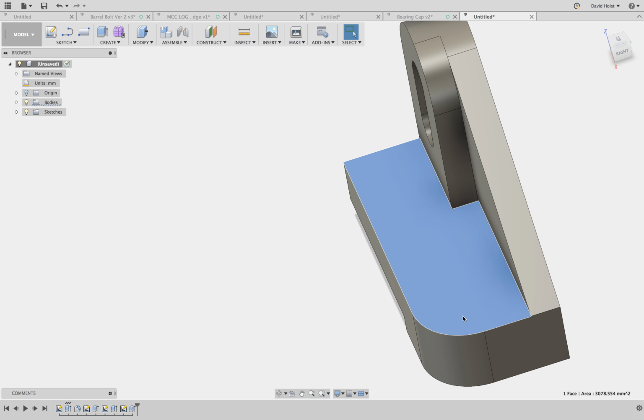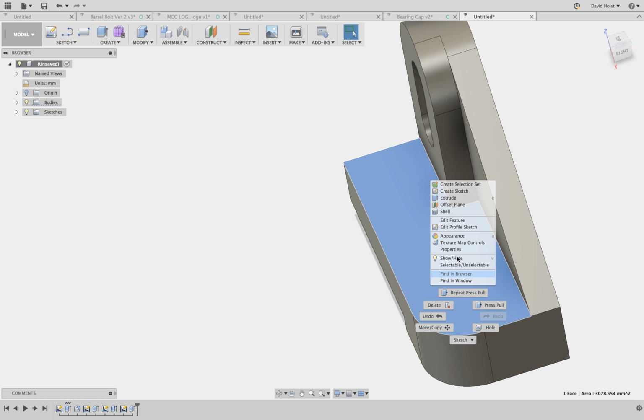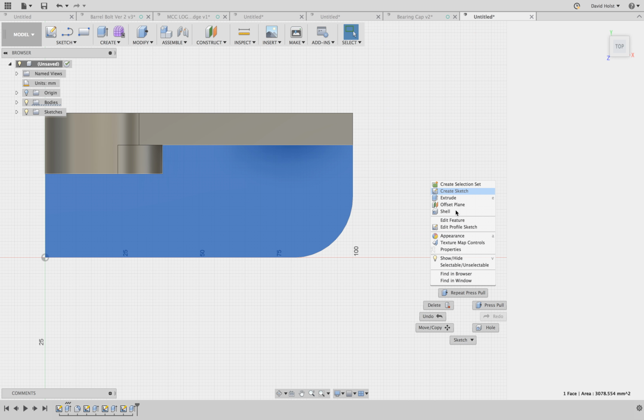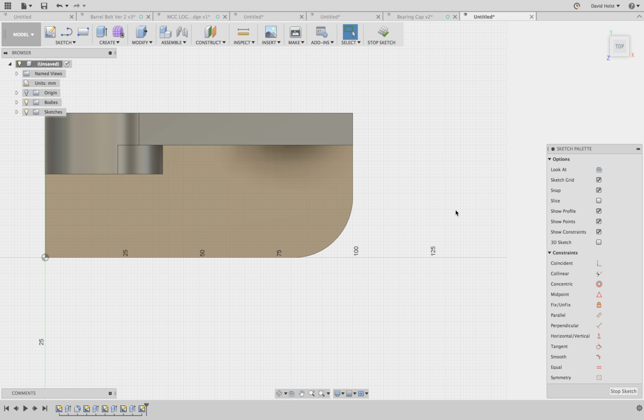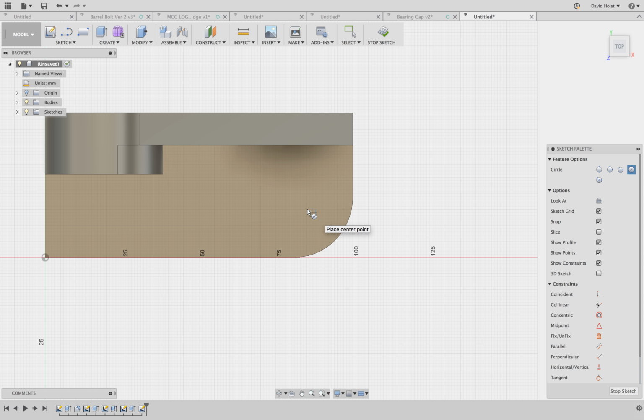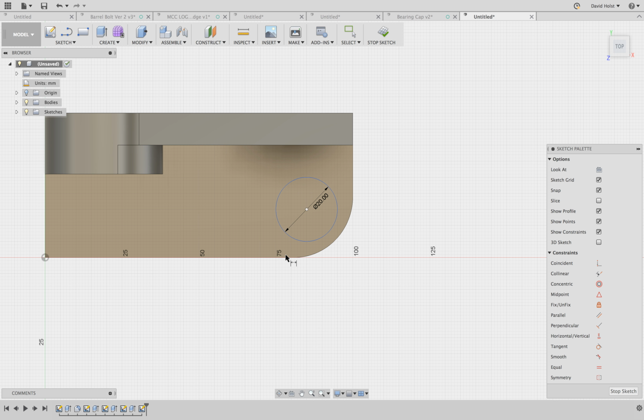Okay. Last one I need to do is just drill this hole on here. Now this has actually got a counter bore on it, so it's actually got like 2 holes if you like, so that the guy's actually countersunk. So we're just going to go at this. It's got a 20mm counter bore, so I'm going to go 20. Now according to the drawing, it's actually 9mm from this edge here, so I'm just going to use my D for dimension tool. Bring that out.